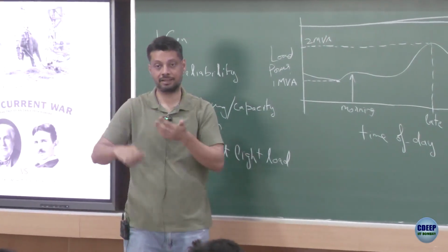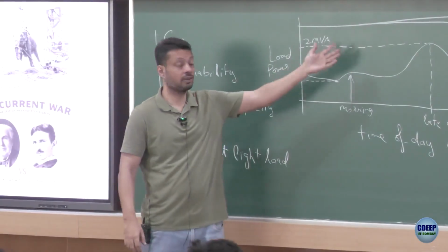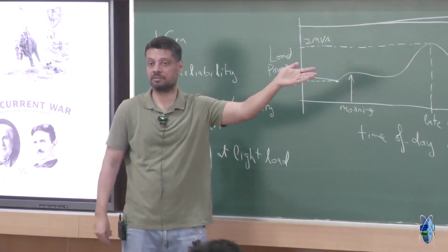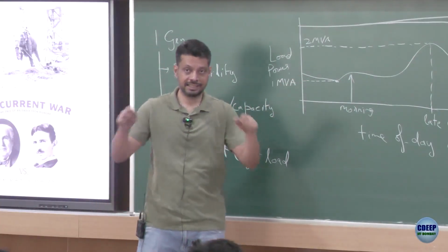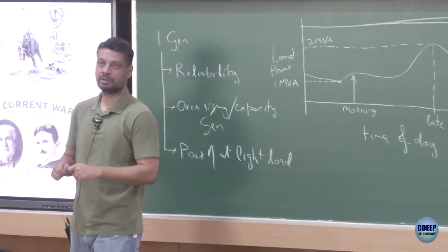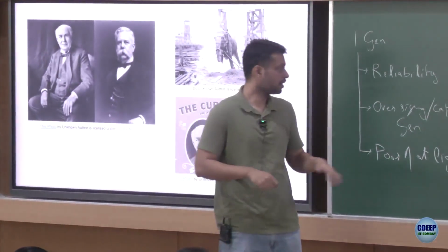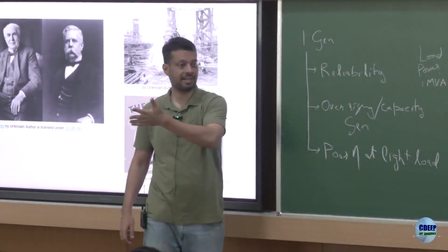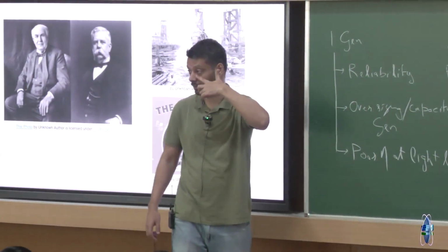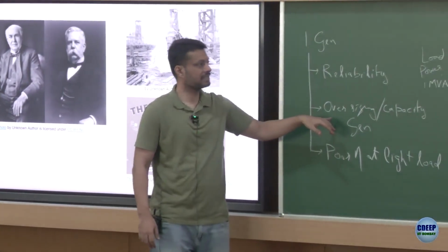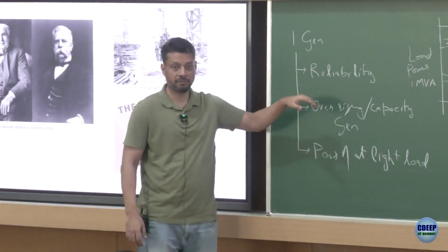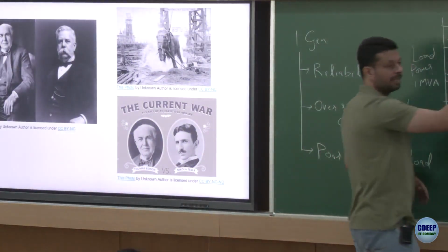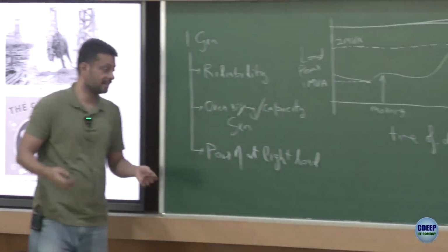I can keep doing that. In the evening, I can probably turn on this generator also, keep the third one on only if required. So if you connect these cities together, right, through a network of transmission and distribution lines, that solves these three problems. Increases reliability because if your generator fails, no problem, you can get power from the other one, right. You don't necessarily have to oversize significantly for your city because there may be other loads who are more here, less here, so they may compensate for it. You don't have to oversize that much.